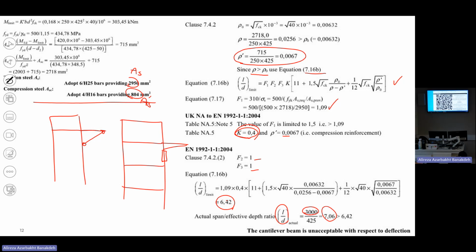Yeah, there are some ways to do so, but there are other solutions like pre-tensioning, post-tensioning, etc. But without this kind of support or without modern technologies, usually you cannot design a balcony with a length of more than 1.2 meters. A 3 meter balcony design is really very difficult to do. That's why the deformation is not okay.